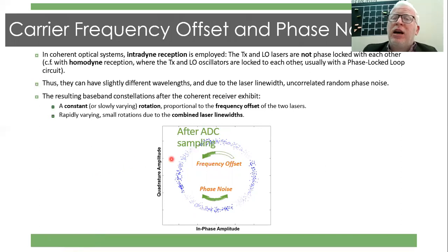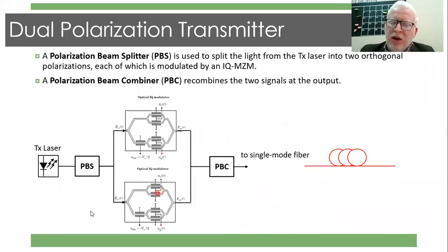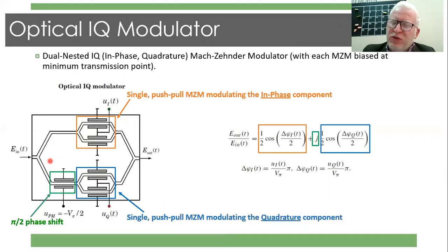generally speaking, as in the RF communication, we have sources of error or sources of noise. Similarly here, we have also some sources of noise, mainly in two regions. The first is what's called the wavelength or the frequency mismatch. I mean, for example, you have a laser that should work at, for example, 800 nanometer, a red infrared laser. In this region, if the generated beam from the laser is at 810, then there is a big shift in your calculation,